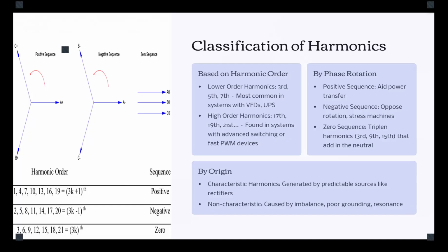it's zero sequence. Now, you might say, if we have a frequency, how come it would not rotate at all? You can imagine the triangular characteristics of the sinusoidal waveform. When we have three phases and we add them together, the summation of the three sines that have a 120 degree phase difference is going to add up to zero.